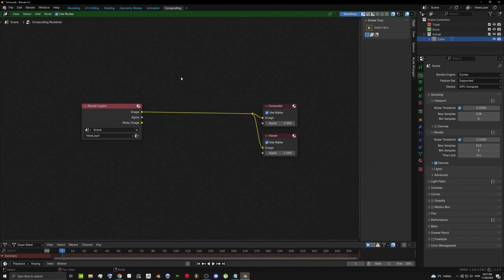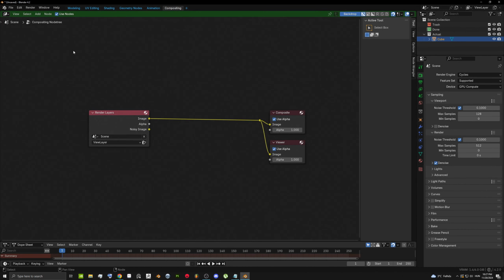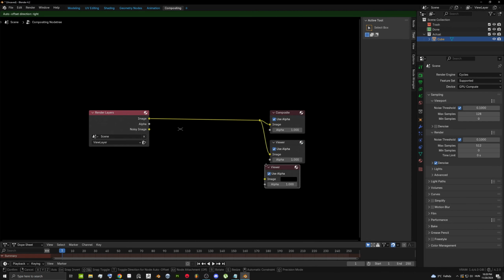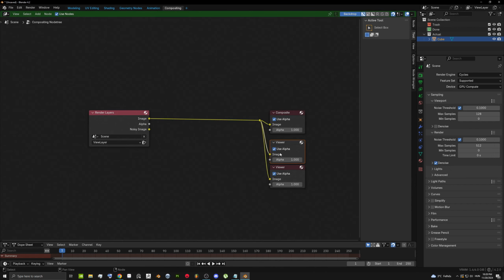And finally, in the Compositing tab, check the Use Nodes box and add a viewer node. You can slice the line with Shift and right mouse button. This is useful for later renderings, so that you can immediately add the desired effect to the image or video.